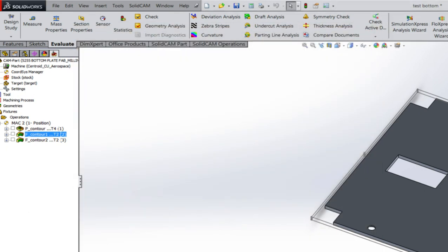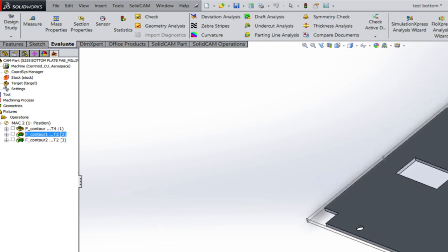You might forget to do that, and if you walk away from this machine, it will run into those clamps and crash it. So you should never walk away from a machine until you have an absolutely proven program that's run once already. Because if you're standing there looking at it, you can hit the emergency stop button and stop it. All right, other questions?